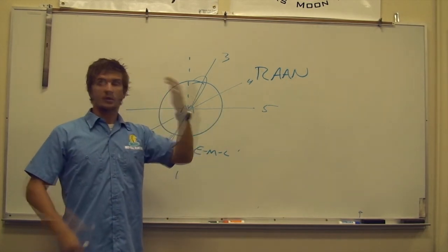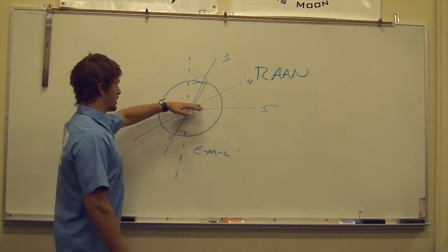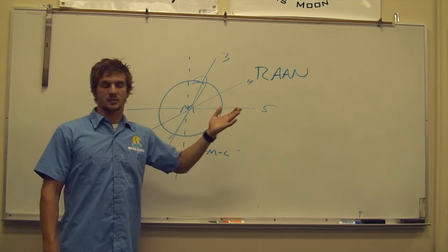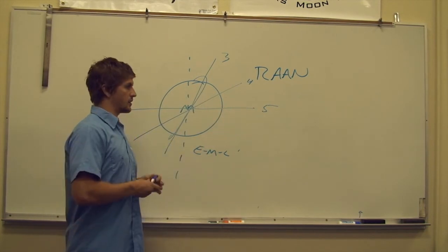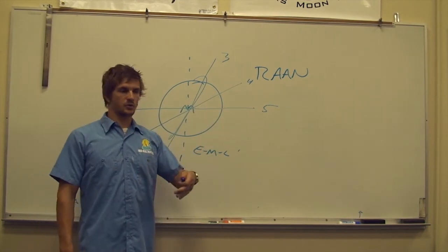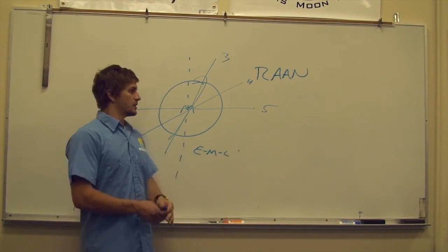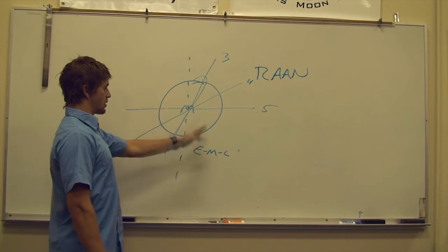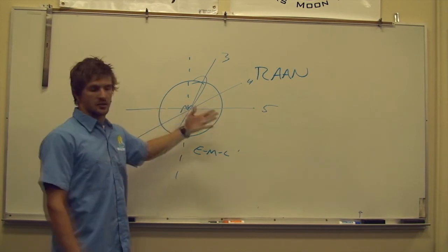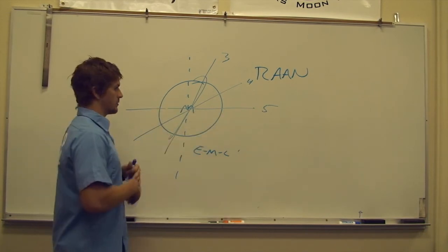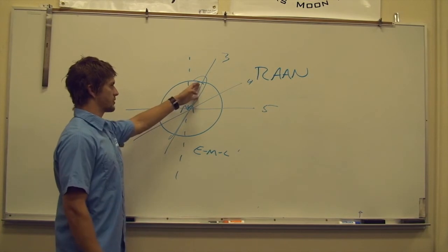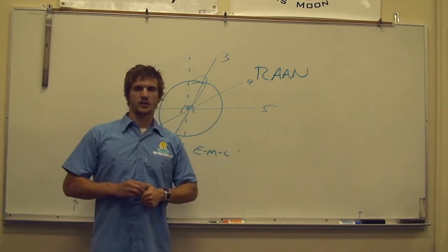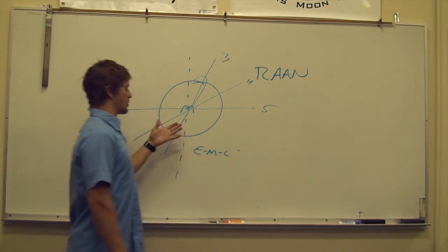So how can you fix this? How can we adjust our plane here to land on our specific target site? There's a handful of ways to do it. The first one, you can adjust your time of flight. So say you're on a 5-day trajectory, well maybe that's going to skew you way off the Earth-Moon line, so go ahead and speed yourself up and lower that trajectory, get yourself into a 3-day, maybe a 4-day, and put you over close to your landing site. The other one, you can just stay in orbit longer.